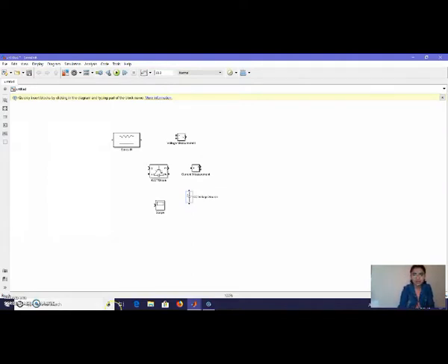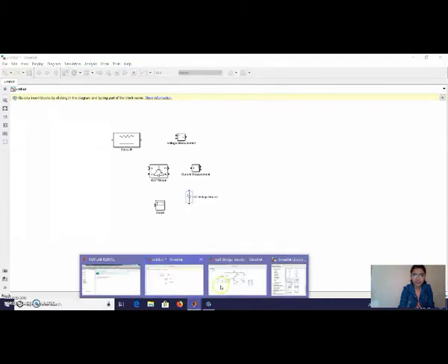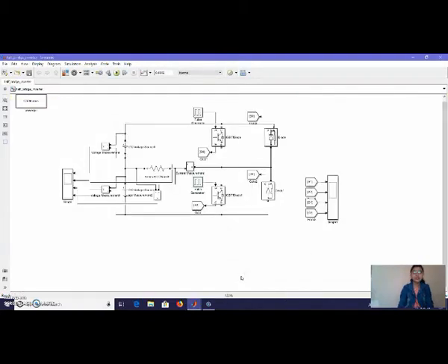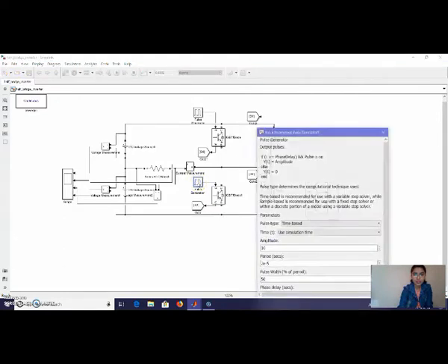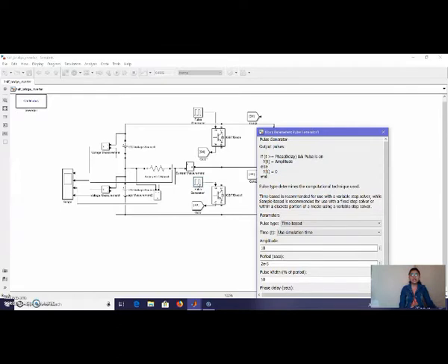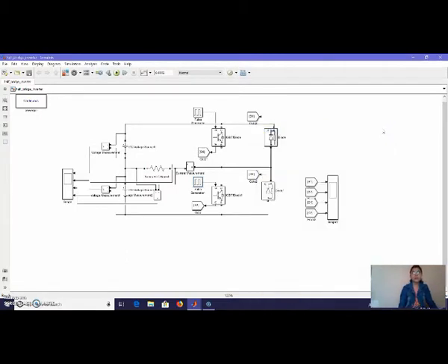So for instance, I have created a circuit of half-bridge inverter. Recheck the properties. Now double click on either of the pulse generators. So set the frequency. Make sure that the other one is opposite so that both IGBTs won't turn on together. I have made the connections accordingly. Make sure that you have selected all the components and made the connections properly.